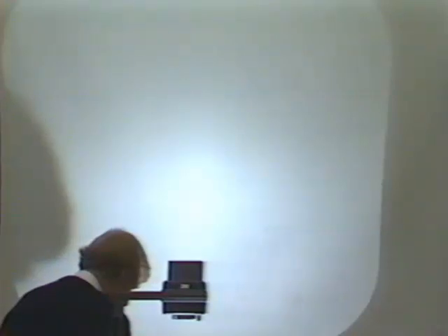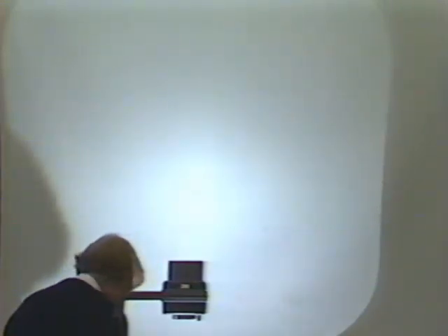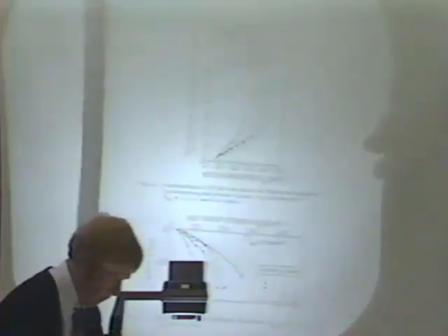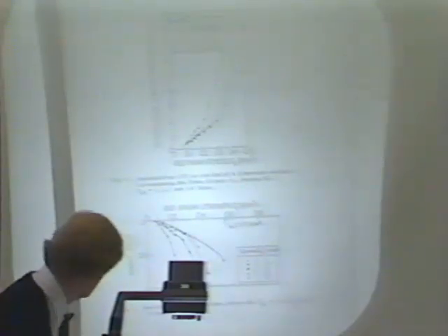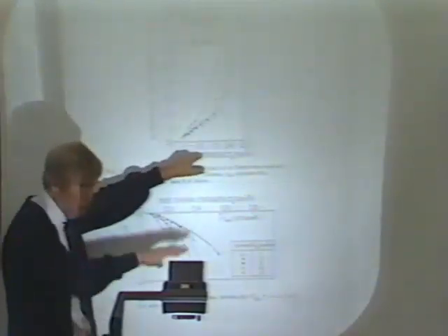Professor Maida's students also observed something like that. This is bed shear stress for erosion, eroding the material as a function of suspension concentration, and they eroded some material to some depth, and then it became more difficult to erode it. And it changed with time. This is 1 day, 1.7 days, and 5.6 days.